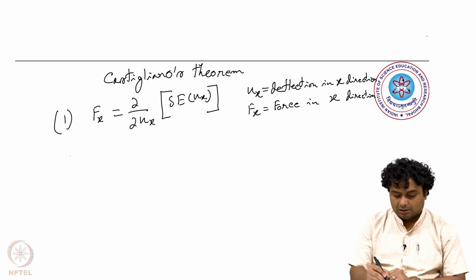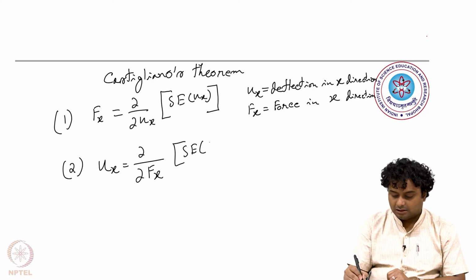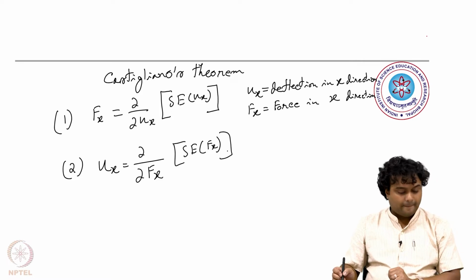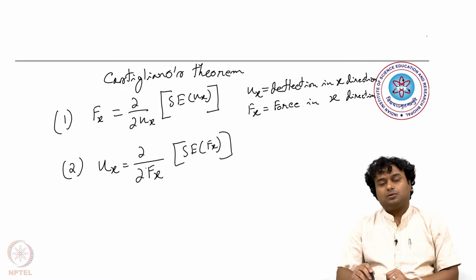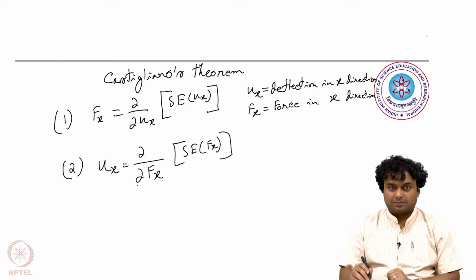This is one of the expressions, and the second expression is just the vice versa, that is, Ux, the deflection, is the partial derivative with respect to the force of the total strain energy, expressed in terms of the force. Now these two expressions we will use for solving different complicated structures, but we are not going to discuss how these two expressions come about.